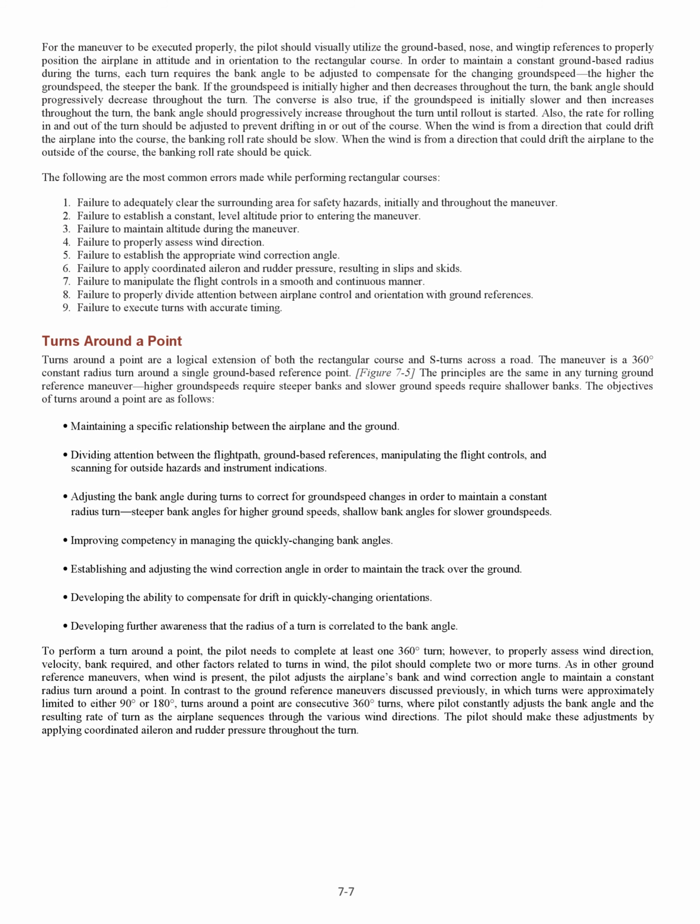Turns around a point. Turns around a point are a logical extension of both the rectangular course and S-turns across a road. The maneuver is a 360 degrees constant radius turn around a single ground-based reference point. The principles are the same in any turning ground reference maneuver.